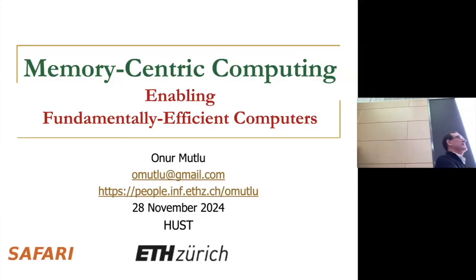In fact, in our earlier work, Tesseract, that I mentioned, our argument was that you want performance that's scalable with memory capacity. In today's processor-centric systems, your performance doesn't scale with memory capacity because you have a bandwidth bottleneck, a data movement bottleneck. If you actually have computation capability on the memory side, your scalability can be even better than today. Does that make sense? Of course, this needs to come with power costs, as was mentioned earlier, and heating that you need to deal with. But fundamentally, I think the scalability of processing near memory is maybe even better than existing systems.